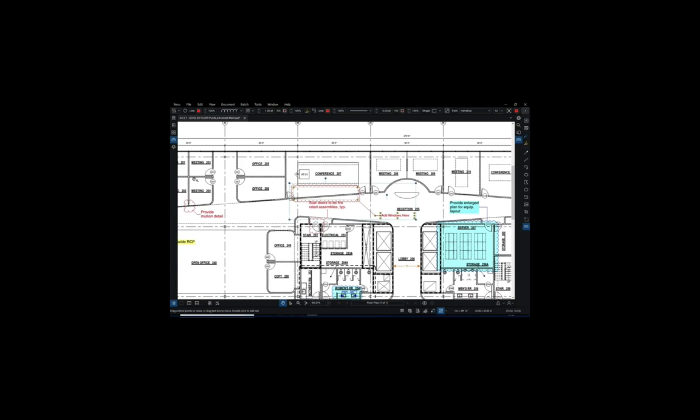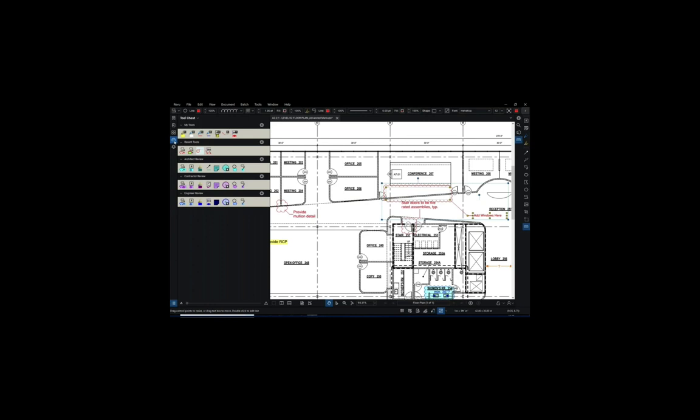And the nice thing is, every time you use a tool, over here in the tool chest, you can see that under recent tools, Bluebeam remembers the tool and its preferences. And if I like using it the way I had it set up in the preferences, I simply double click on it, drag it onto the drawing over and over and over again. So you can see how quickly, if you have similar markups to use, how your recent tool chest is very helpful.